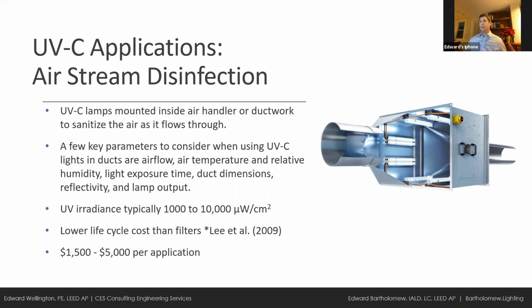The velocity of the air going through the air handler or duct is a main consideration. You want an absolute minimum of about 1/4 second exposure time, but ideally a full 1 second is better. So again, if you're moving that air relatively quickly through that duct or air handler, you'll need a longer section of duct for that treatment.